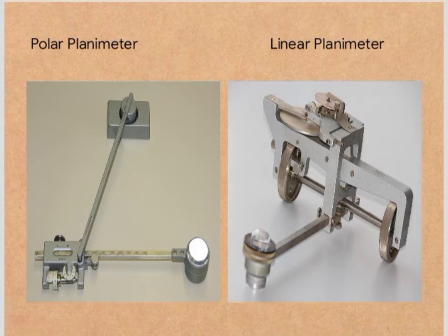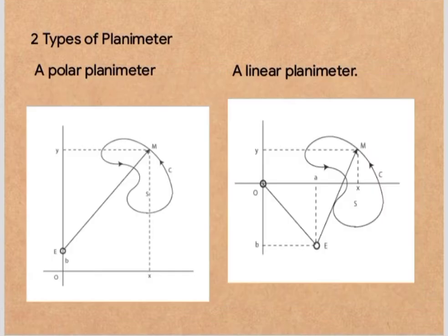The two planimeters differ in the movement of the end of the tracer arm opposite to the tracer point, and I will explain that one by one. So let's have first the linear planimeter. That end is restricted to move along a straight line, from the word linear. The drawing suggests that it runs along a track, but a more common way to cause this motion is to move this end attached to a set of wheels that are fixed to an axis so that the wheels turn together.